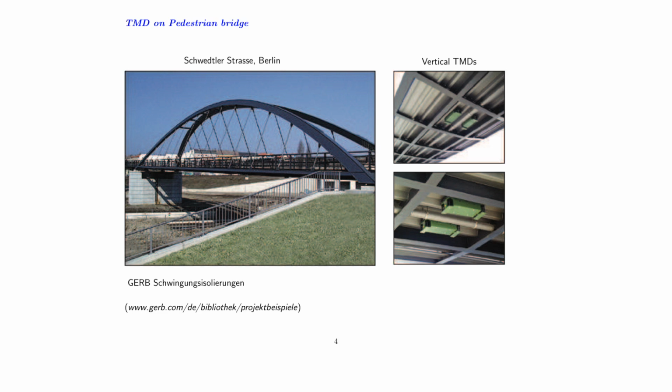Pedestrian bridges nowadays are really slender. Have a look at the bridge to the left. You have a very nice and slim deck structure, with almost no height of these box girders. Then you have a fairly slender arch, and you have the cables supporting the very slender box girder so that it is supported by the arch. So in general, pedestrian bridges are what we refer to as slender. So they're really prone to dynamic amplification, for instance, from people walking on the bridge.